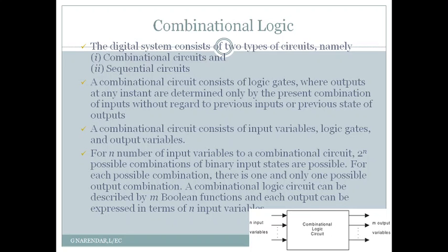So that means, to store the previous inputs or previous outputs, we can say that the sequential circuit consists not only of logic gates, but it should also contain memory elements. So this is the difference between combinational and sequential circuits.